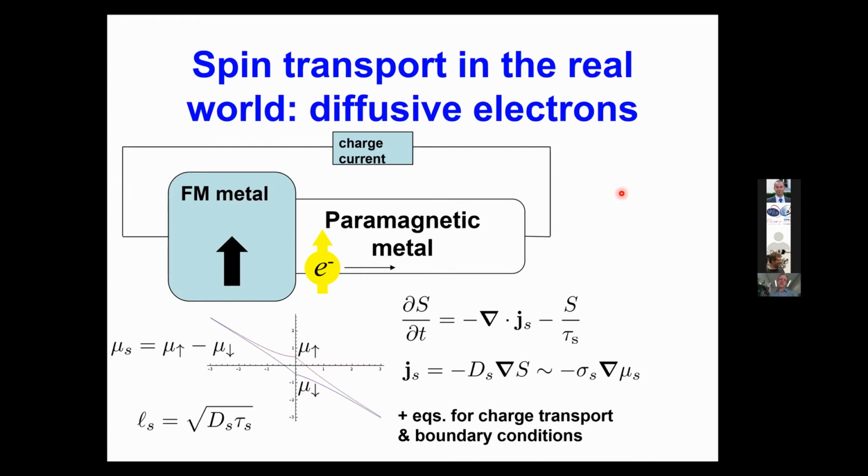So this is kind of the first way that it was established, I think, historically in the field of spintronics. Now I'm going to talk a little bit about how that works. In practice, what you often do to establish an electronic spin accumulation is to drive it with a charge current from a ferromagnetic metal.